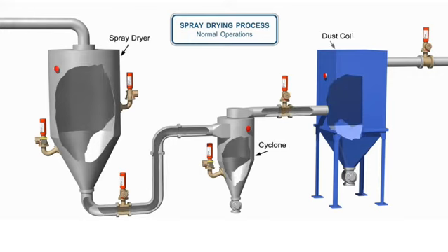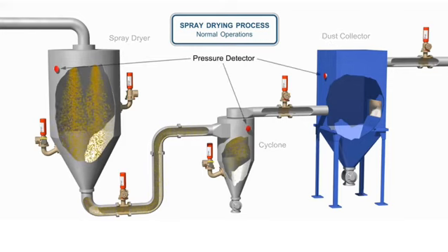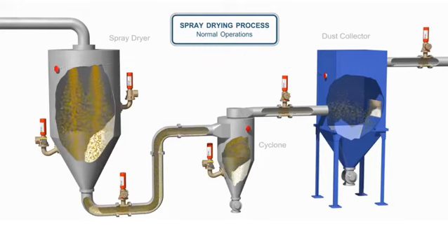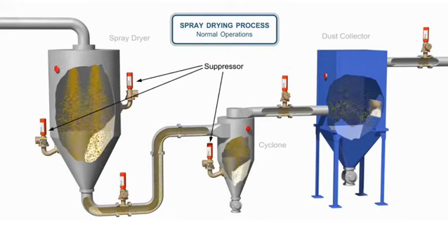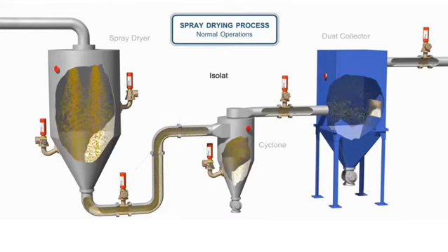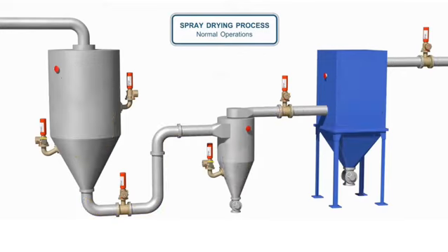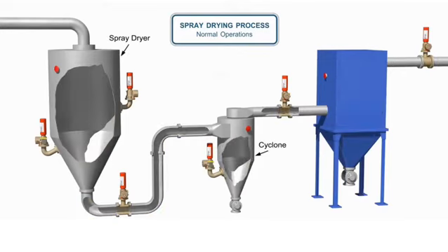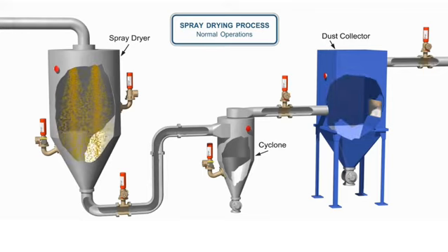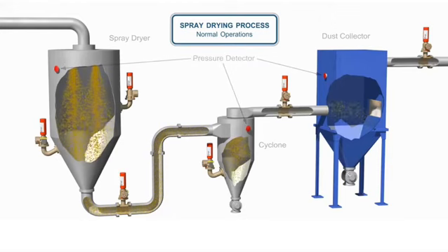However, spray drying does have some limitations. It requires high energy, making it costly to operate. The equipment is expensive and complex, so it's typically suitable only for large-scale production. Some heat-sensitive nutrients, like vitamin C or certain proteins, may degrade if drying conditions are not carefully controlled. Very thick or oily liquids are difficult to process efficiently, and certain sugars or fats can cause stickiness, sometimes requiring anti-caking agents. Overall, it is a delicate balance between process efficiency and product quality.